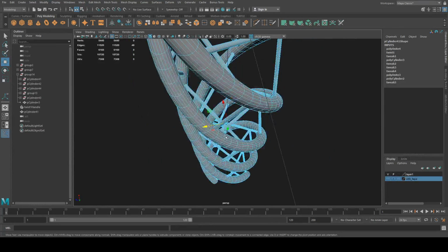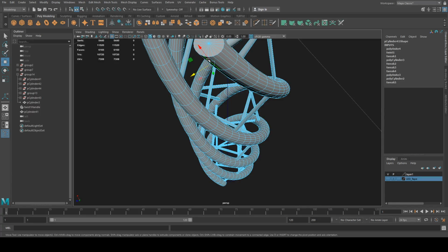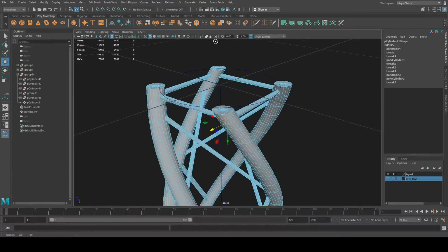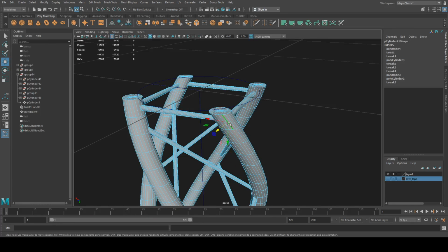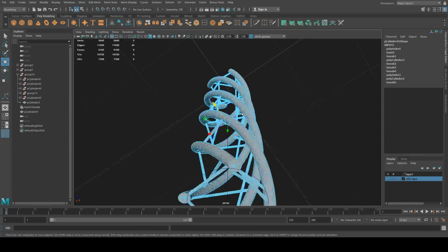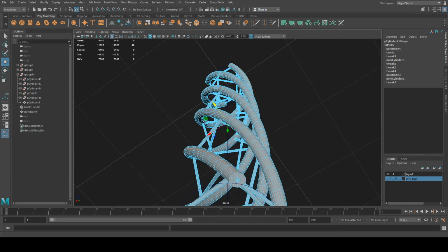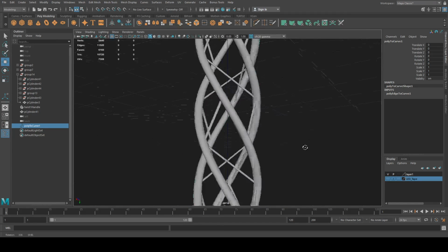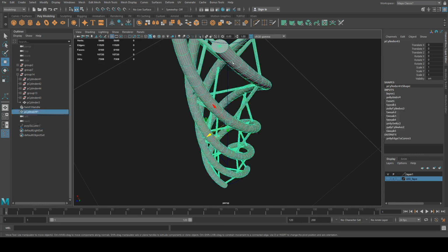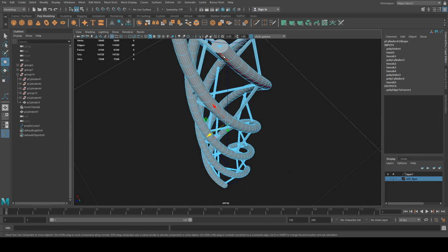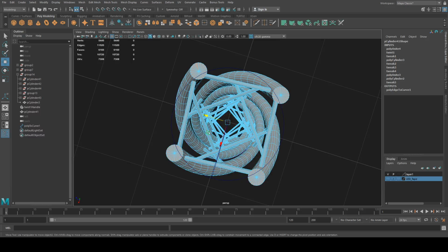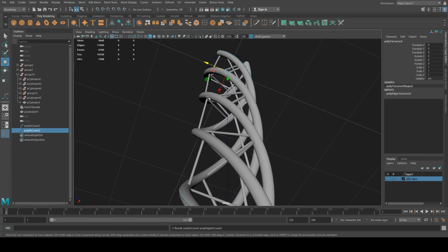So now I'm going to go to display, modify, it's not a particularly good spot. Hold on, let me just see here. Okay, let's get that one. And then let's, okay, so modify, convert, polygon edge to curve. Okay, and now I'm going to grab the next edge next to it. And again, I don't want the top and the bottom bit, so I will get rid of those. And then I'm going to hit G, which is last selection.